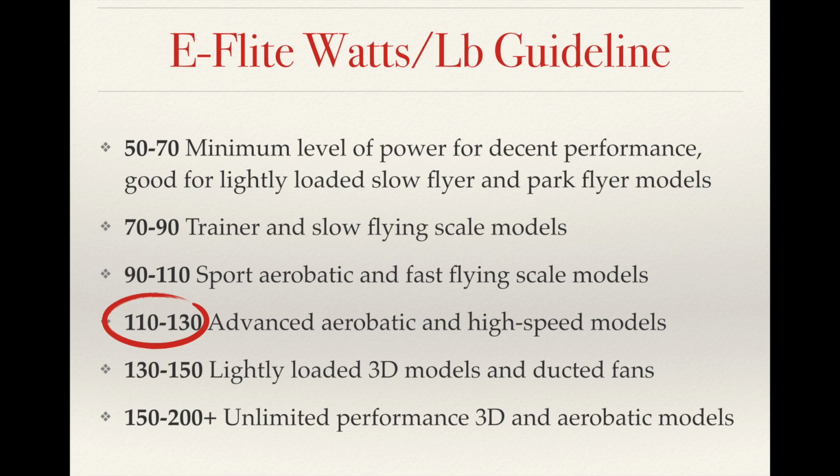You can say, well, I want mine to make more power or less power. I don't need that much power for this type of plane. So you can make your adjustments as you see fit. But it's a good reference and a place to start. So for the example, we're going to use 130 watts per pound. That's just a number that I happen to like. I like the way my airplanes feel when I'm making that kind of power.